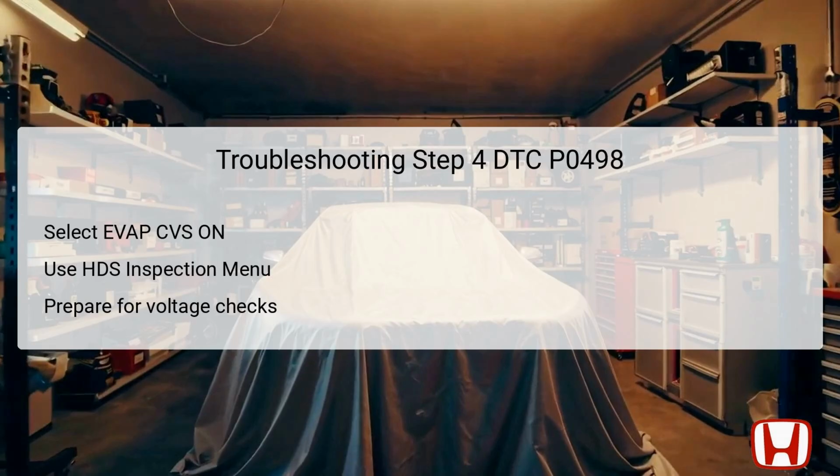Selecting this option prepares the vehicle's system to respond accurately and ensures that the technician can capture real-time data regarding the valve's operational status. This active selection is essential for understanding whether the system can identify faults during its operational phase. Having the HDS set to this mode prepares the technician for the next step involving critical voltage checks, which are fundamental in diagnosing the underlying issues with the EVAP canister vent shut valve circuit.